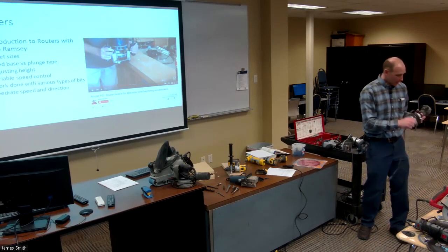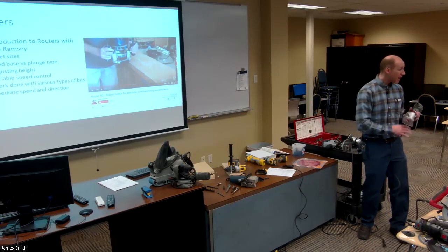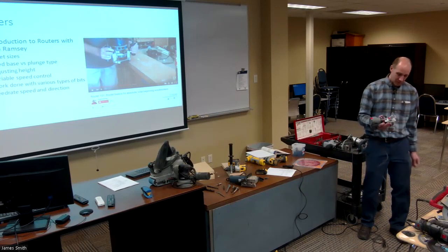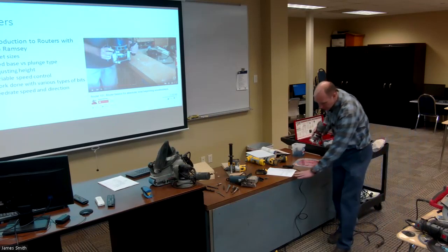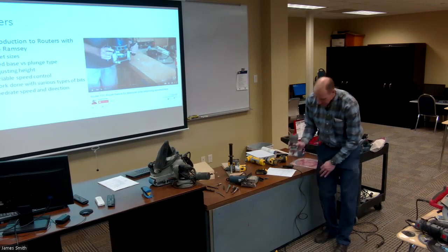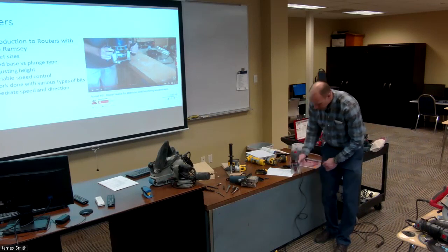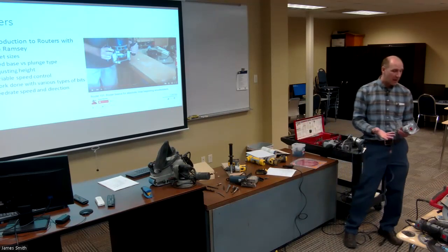But these, I guess, are not called laminate trimmers anymore. People are starting to call them mini routers. But when I was growing up, they were called laminate trimmers because that's what they were used for. When you were gluing laminate onto a countertop surface, you would use a flush cutting bit and you would just run it and trim up the laminate. You didn't need something that was very heavy duty.